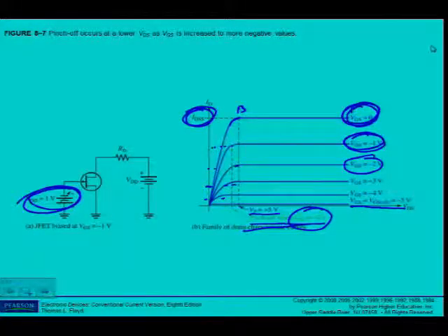Okay, so also what you can see is that value, because of the curves, becomes smaller. Alright, so depending on where we are on the curve, I can see that the pinch off voltage becomes smaller, but V pinch off is determined at VGS equal to 0 at IDSS, maximum current. Alright, so make sure that you distinguish between those two.